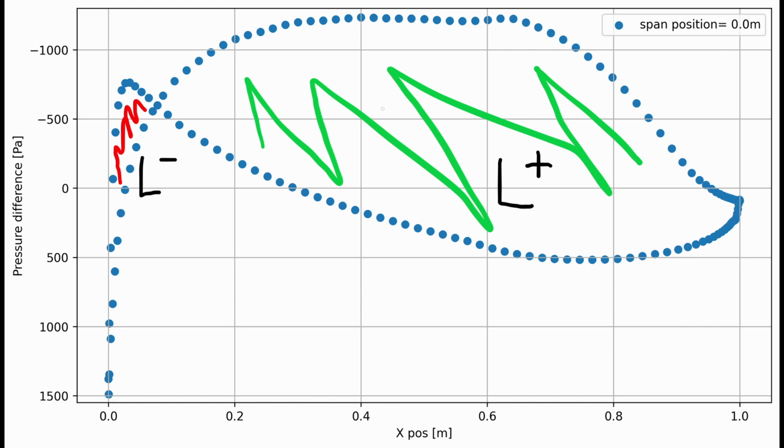This pressure force mostly acts in the y direction, so the direction where our lift is pointed. There's also a small component acting in x direction. This is just due to the fact that pressure always works normal to the surface, and our airfoil is curved. You can see we have a fairly large closed-off area between the two curves, which would generate positive lift, and then a smaller area close to the stagnation point, close to the leading edge, which creates negative lift.